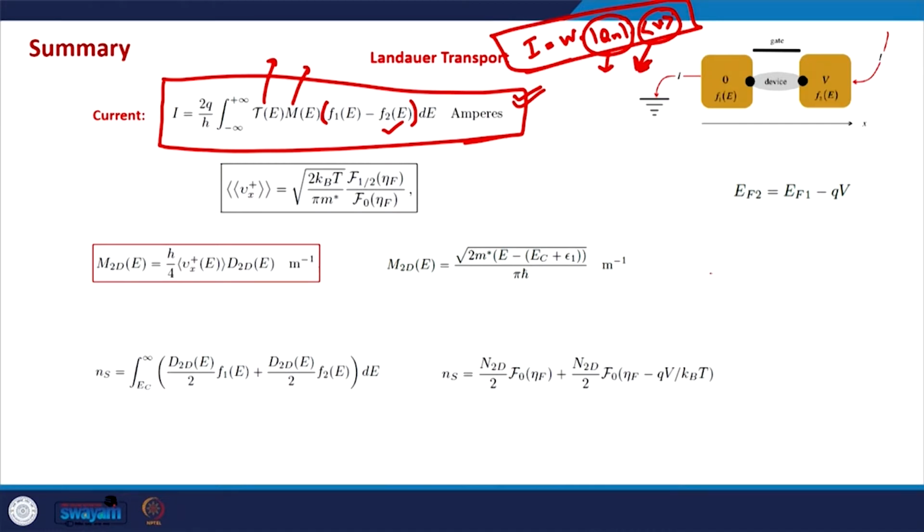In the MOSFET, if we plot the barrier profile, this is how it looks. This is the source side, this is the drain side, and this is the energy landscape in the MOSFET. This is the point, or rather, to be more precise, it is right at the start on this side, very close to the source. This is the point where the electric field is very small, and from where electrons start their journey to the drain side, and a drain current is set up in the device.